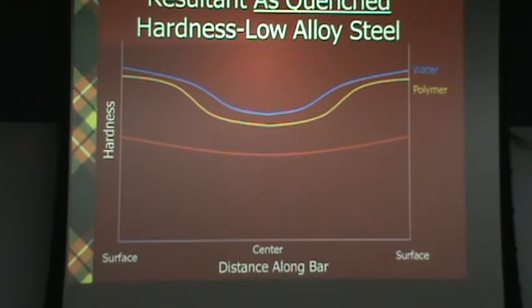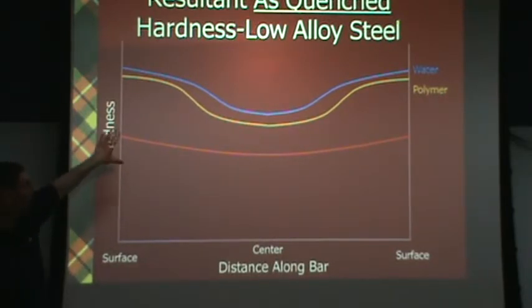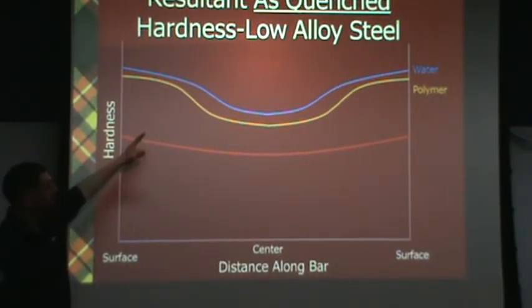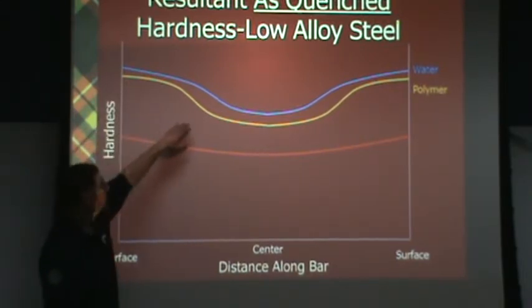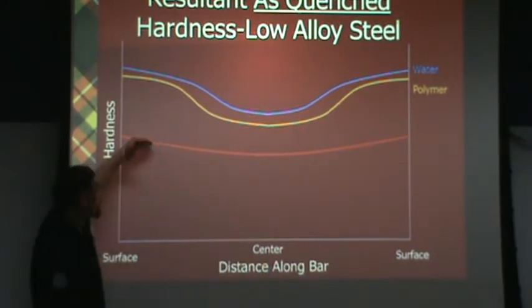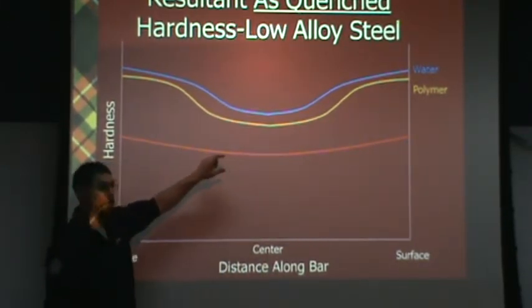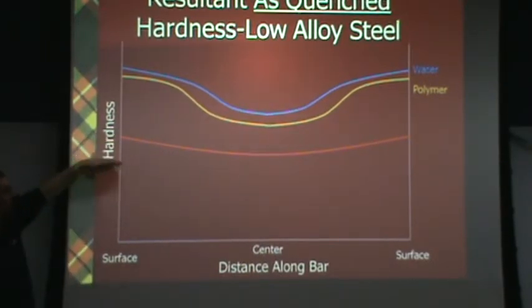So here in this case, instead of showing different alloys on the same graph, now we're showing different cooling rates of the same material on one graph, right? So here we have the fastest cooling rate, intermediate cooling rate, slower cooling rate. The slower cooling rate is going to have less variability along the diameter of the bar, but it's also going to have a lower starting hardness.